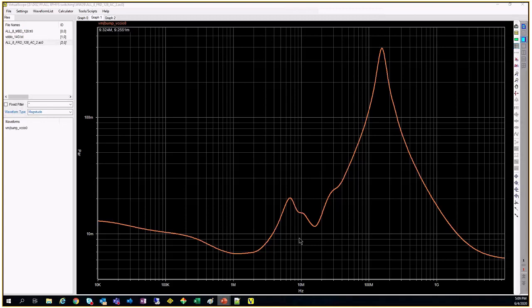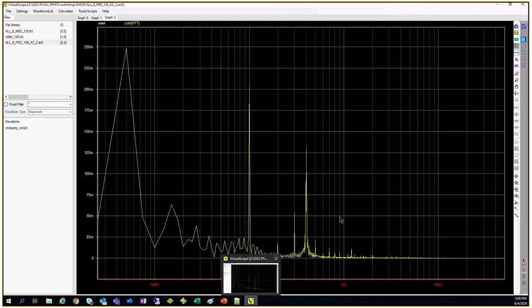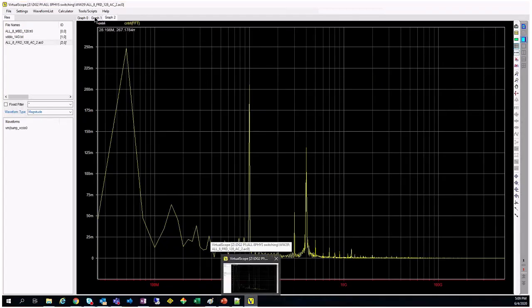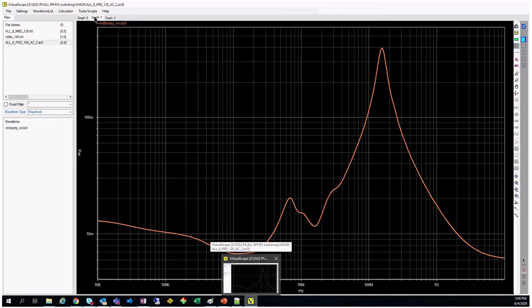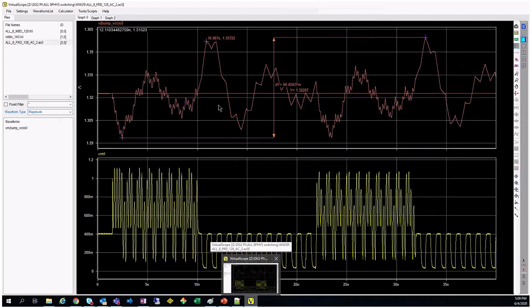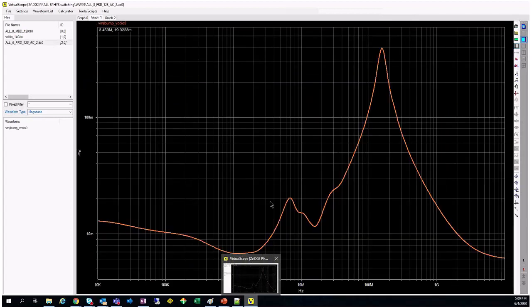By bringing this impedance down as much as possible at different frequencies, when you multiply it by whatever current you get, your eventual voltage swing is less, right? The voltage drop. So our aim is to reduce the impedance. Let's say at 10 megahertz, now it is 18 milliohms.